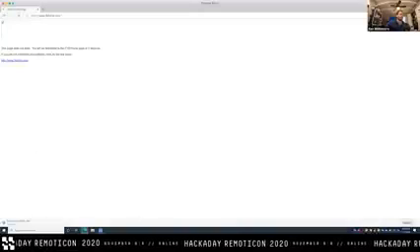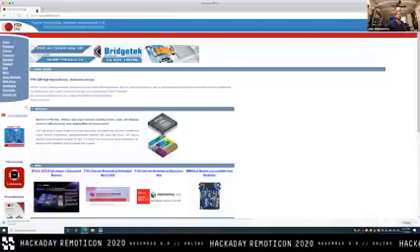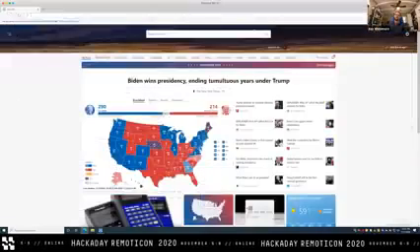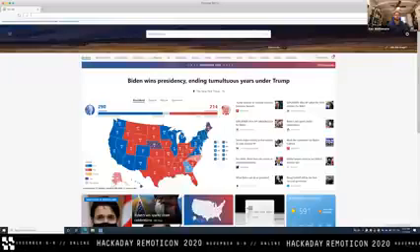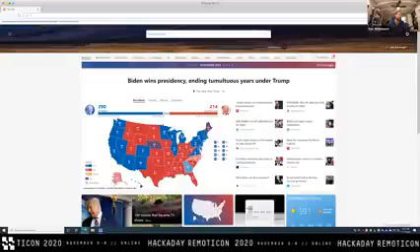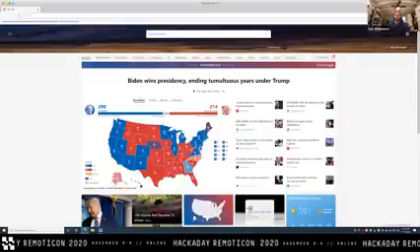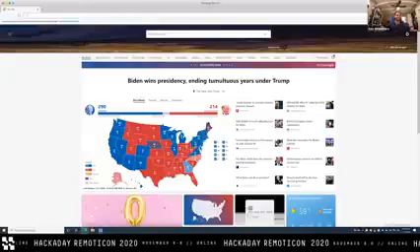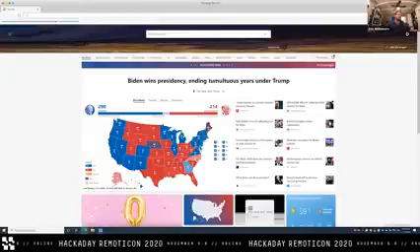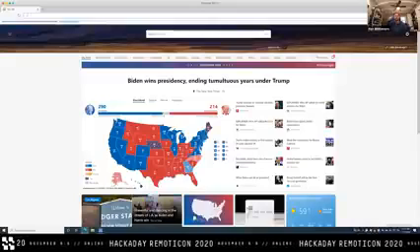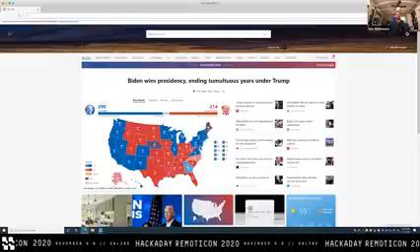Okay. Well, anyway, long story short, if we look at the data sheet for the FT232H, we see, one, it does indeed use a 12 megahertz oscillator. So that thing that had 12 on it and looked like an oscillator was a 12 megahertz oscillator. Surprise. It also has a couple of interesting features where it pipes clocks out on a couple of different pins. So it has a couple of different clocks that it'll pump out. I don't recall exactly what they are, but one of them is a 60 megahertz system clock that all of the other devices in your system are supposed to be synchronized to.